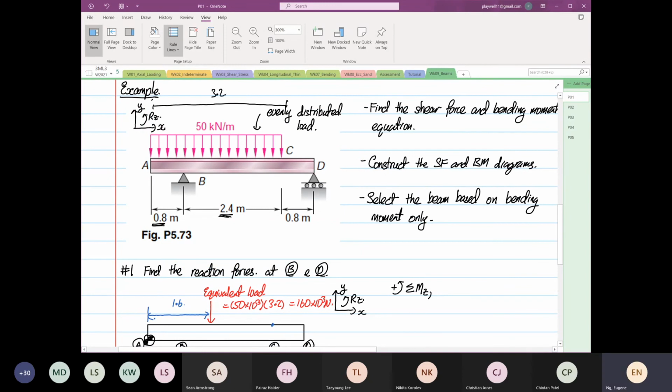3.2. The equivalent load will act in the center. That's why it's 1.6. Christian, does that make sense? Yes, thank you. Okay, so this is why it's 1.6. If it's a triangle, it's L over 3. Yes or no? Where the L over 3 is from the higher magnitude of the gradient distributed load. Okay, so I think that was covered, or I've sent a video out on that.